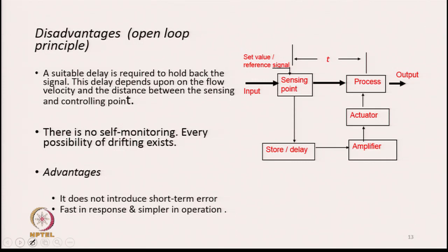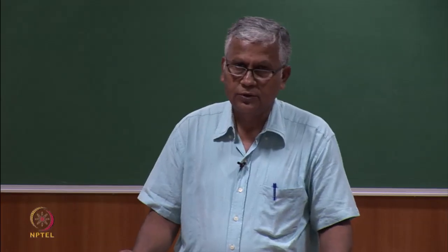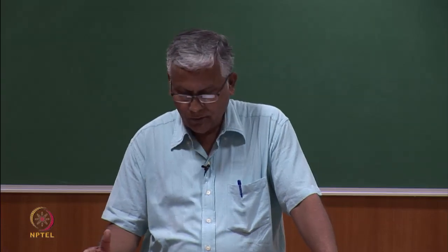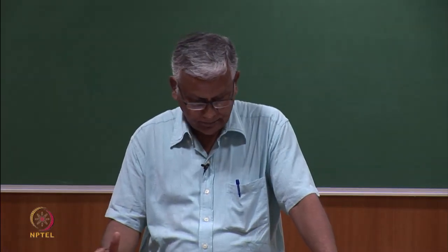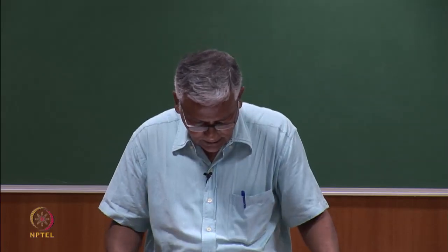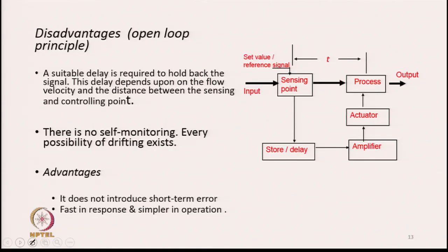We have to hold back the signal for some time, because there is a distance between the sensing point to actual control point, and this time t depends upon the velocity of flow of the material and the actual distance between the sensing point and the process where this action to be taken. So, delay is one thing that we need here.